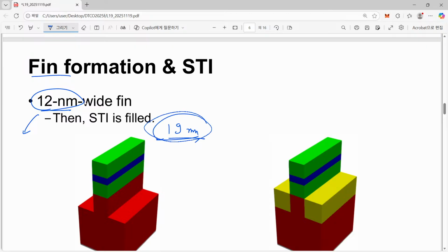So it means that a 19 nanometer line with a much larger distance or larger pitch, about 60 nanometer scale, really makes our life easier than FinFET. Please remember our ASAP7 case. The fin pitch was 27 nanometer, and the fin itself was just 7 nanometer thick.